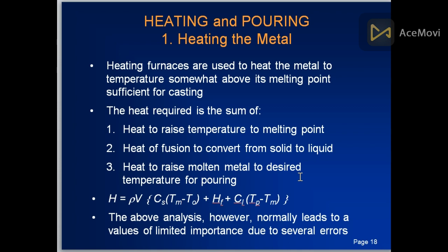For example, the metal melts at 1700 degrees centigrade, but there is some time for pouring and traveling, so we must raise the temperature to approximately 1850 so that it takes some time to solidify.